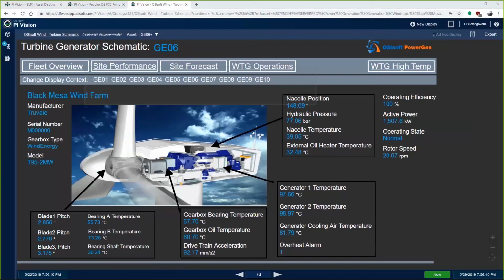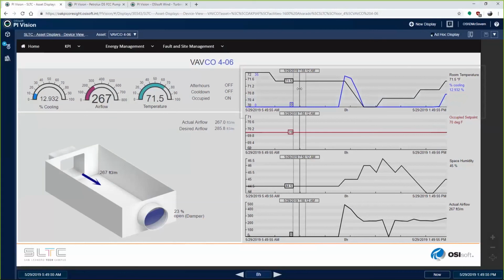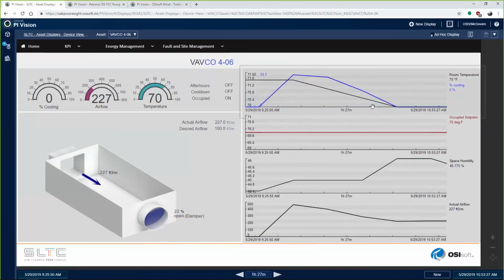Is it possible to click on an event from the events table and have it place a bar or marker for that instance in time on the process measurements? So you can. One thing I didn't show: if you click onto trends, it'll drop a line in here and tell you the value of all of these sensors at this particular time. I can click and drag this timestamp, and it'll tell you about those. If you were concerned about what was going on at a particular time, you can click and drag to zoom in, and you can drop a line on here to find out what the exact value was at this time. But can you just read that question one more time?